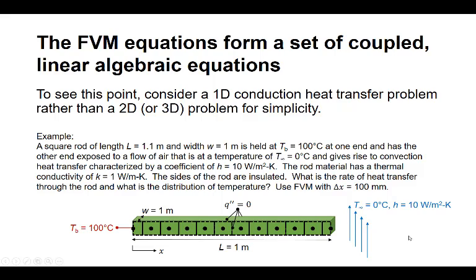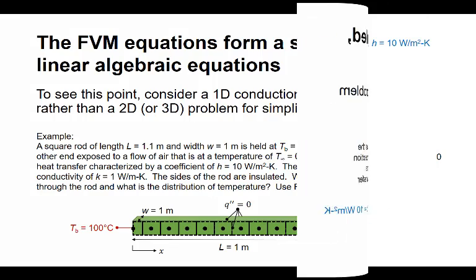And even though we could tackle this problem using a thermal circuit, and we in fact will do that later in the lesson, we are going to tackle this problem with the finite volume method in order to demonstrate that the equations form a set of coupled linear algebraic equations. Here we have established a numerical mesh with a node spacing of 100 millimeters. That's the first step in the finite volume method.